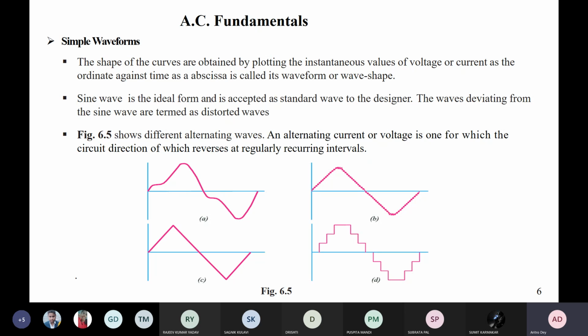So even if you have a step input like this step response, or you get a DC value like this, you can get it in terms of sinusoids. Like this is your fundamental, then you have your third harmonic, then fifth harmonic. Okay, if you just keep on adding this, you will get some ripple over there, but you will be able to construct the same pulse as it is shown here.